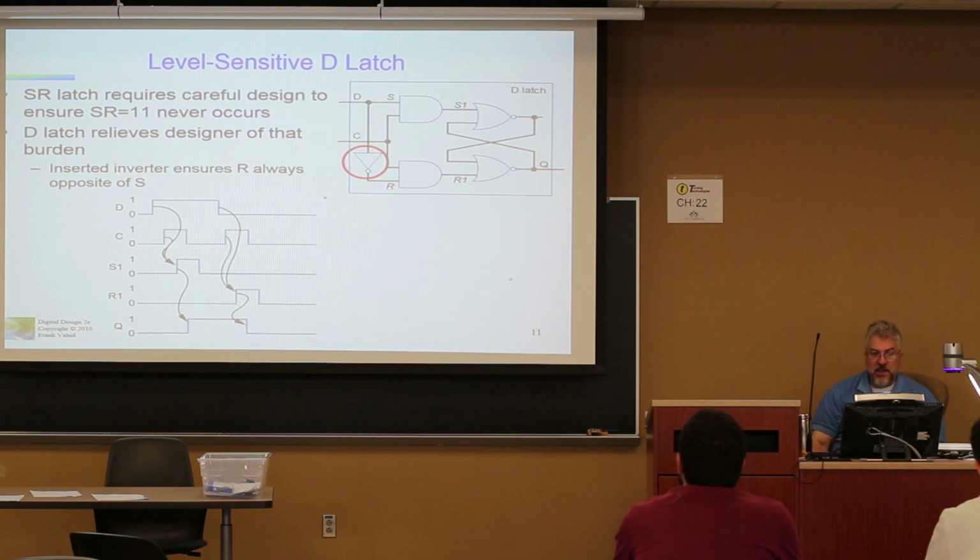If you look at the timing diagram for this, when you raise D, nothing changes until the clock comes in, and then the S input will go high. Notice that when the clock goes down, the S2 input goes back down, but by that time you have already passed the information along the T up here and then eventually to Q.